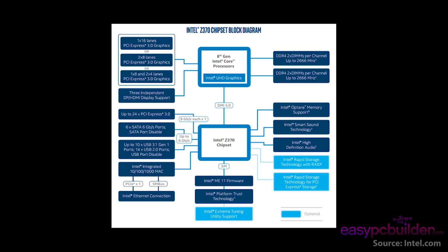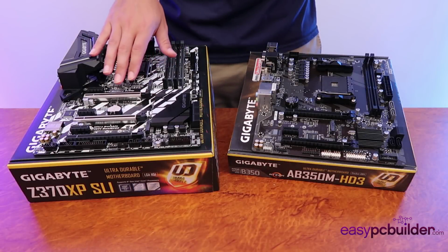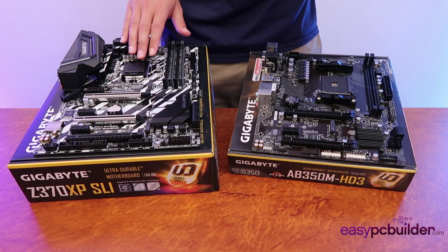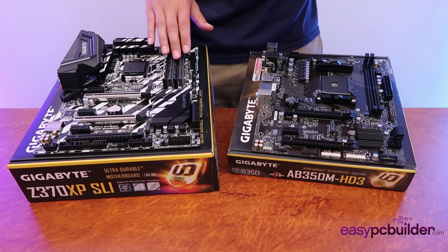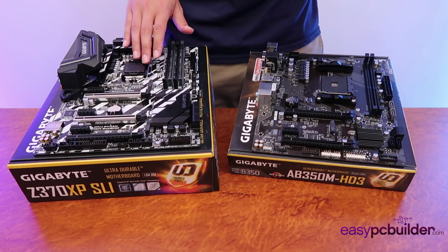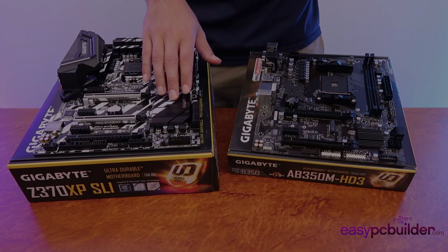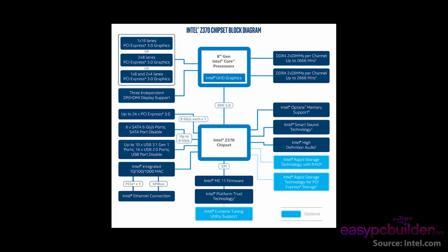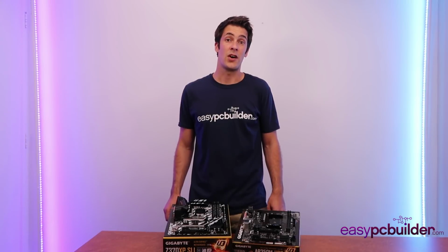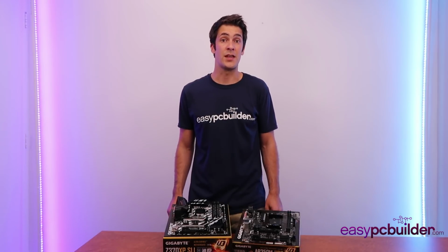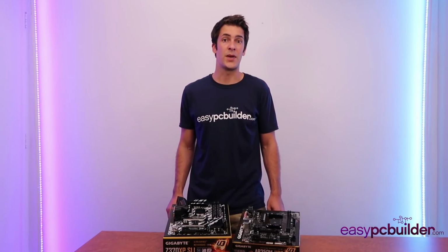Due to the large amount of data being transferred between the RAM and the graphics cards, the CPU now controls the data flow from the RAM and the graphics cards directly, interfacing to the motherboard chipset for the lower bandwidth tasks such as USB, SATA, networking and other slower PCI Express slots. So one chipset type can support a manufacturer's CPU of many different speeds and cores, but the type of chipset that you choose is dependent on what you want to use the computer for.